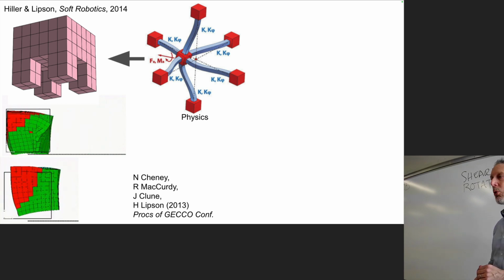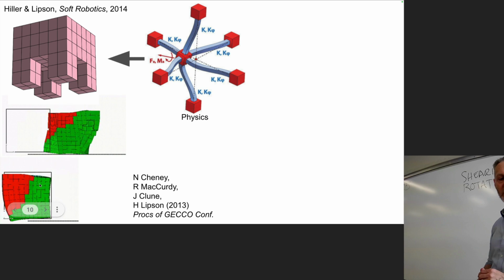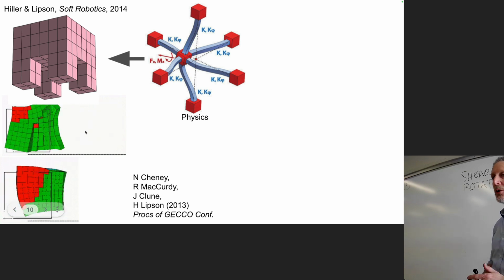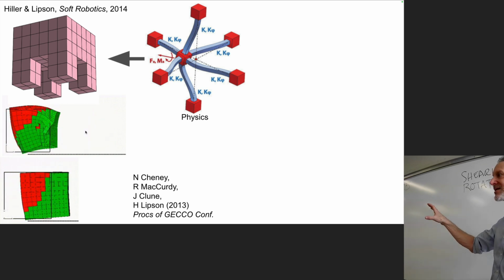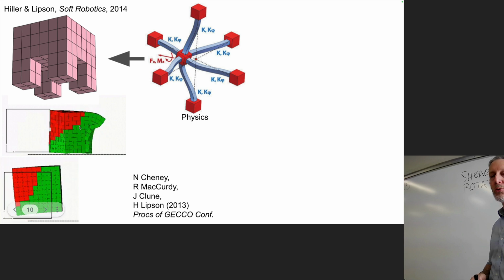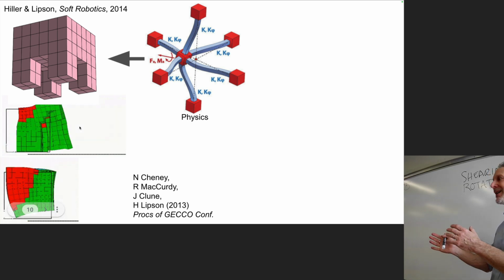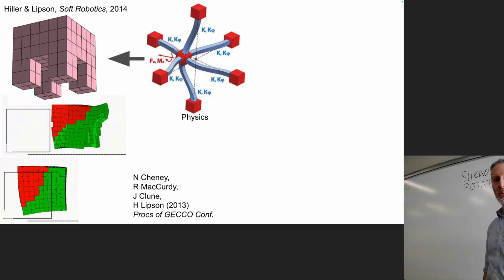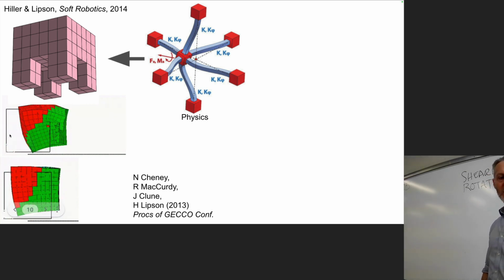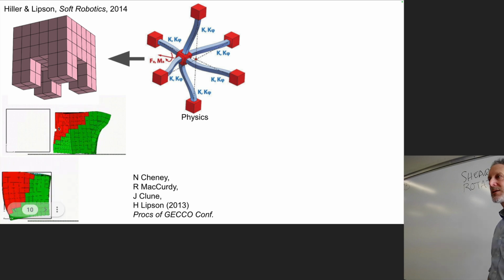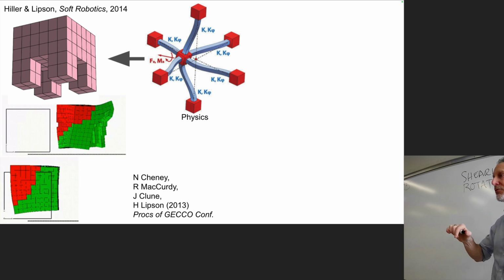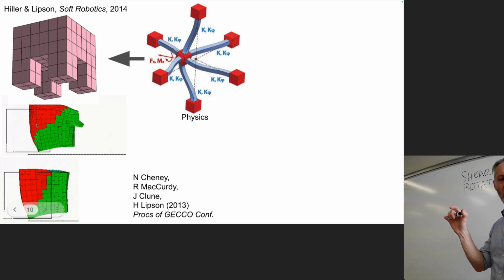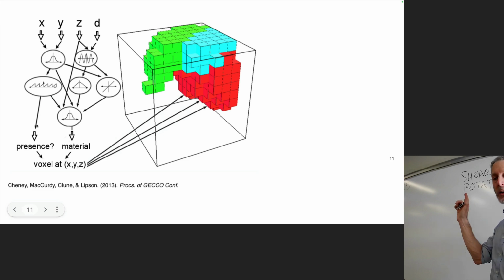And you'll notice here one relatively low fit robot and a more fit robot. So like we were just talking about for your oral presentation, here's some anecdotal evidence that an evolutionary algorithm can find the right 3D geometry for a soft robot in simulation that causes it to move from left to right. You'll notice that some of these voxels have different colors. These colors indicate properties of the underlying beams, the stiffness of the beams that connect those voxels to other voxels. So I'll come back to those material properties in a moment.